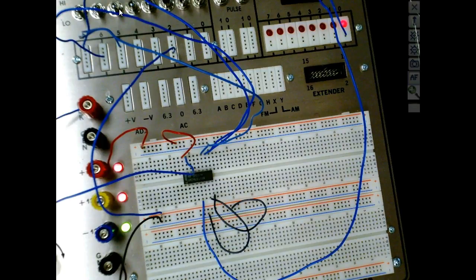So the standard size of the dip stayed about the same width for up to a 24-pin dip. When we got to the 74154, I think I passed this out to y'all, right? They had to go to a 24-pin dip. So look what they did on a 24-pin dip. They just about doubled the width of the IC. And this was around for all your microprocessors spacing.